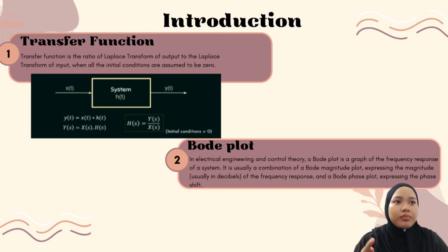It is obtained by applying a Laplace transform to the differential equation describing system dynamics, assuming 0 as the initial condition. The transfer function is actually the ratio of the Laplace transform of output to the Laplace transform of input.